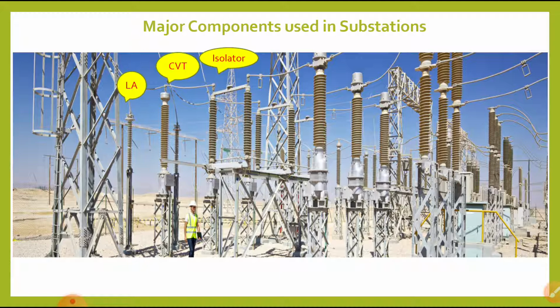In lower cases, I can use an ammeter. I can use a clamp meter to measure the current, but when it is a high voltage and hundreds of amperes, I cannot measure directly. For that purpose, I am going to use some instrument transformers. What are the instrument transformers? CTs and PTs. CT is a current transformer and PT is a potential transformer, used to measure the voltage and to measure the current.